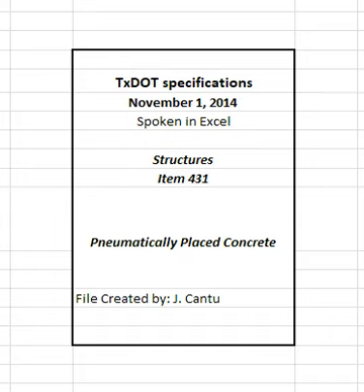Use reinforcement when performing repair work in all areas where the thickness of the concrete will exceed 1.5 inches. Use a single layer of either 2x2 W1.2 x W1.2 or 3x3 W1.5 x W1.5 welded wire fabric, or approved equivalent, unless noted otherwise on the plans. Use a single layer of wire fabric to reinforce each 4 inches thickness of patch or fractional part in areas where the concrete thickness exceeds 4 inches.